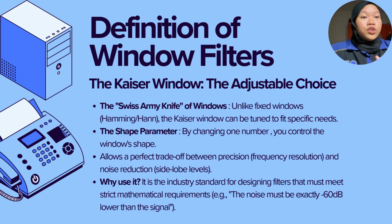Why do pros use it? Because it is the standard of the industry when a filter design has to have very strict mathematical requirements. For example, when a project requires that noise must be exactly at negative 60 dB of the signal, then the Kaiser window is the tool that allows us to tune the filter to reach exactly that goal.